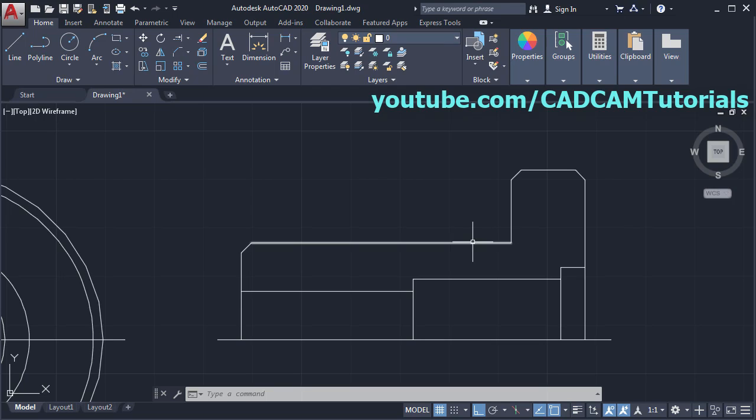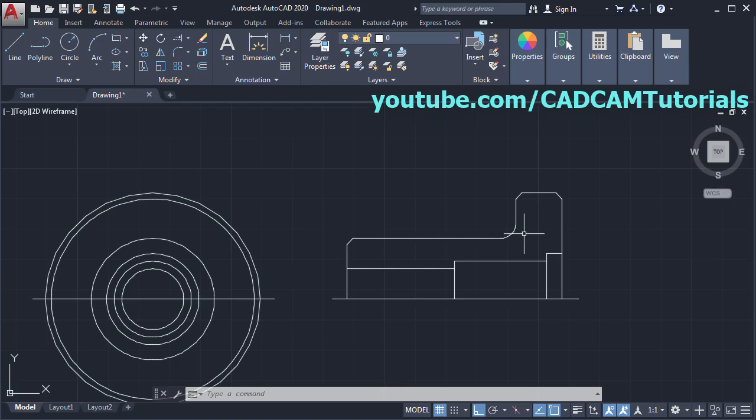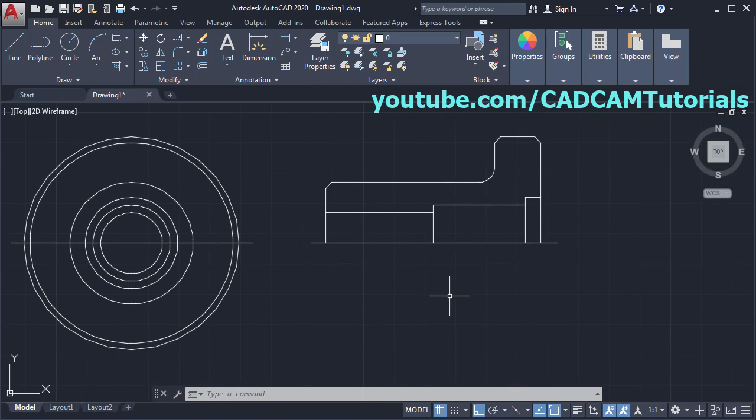Then here is a fillet of radius 5. For that, click here and select fillet. Click on radius, give the radius of 5, enter, and select this line, select this line. Then we want the same on the opposite side, we will mirror it. For that, click on mirror, then select all this object.